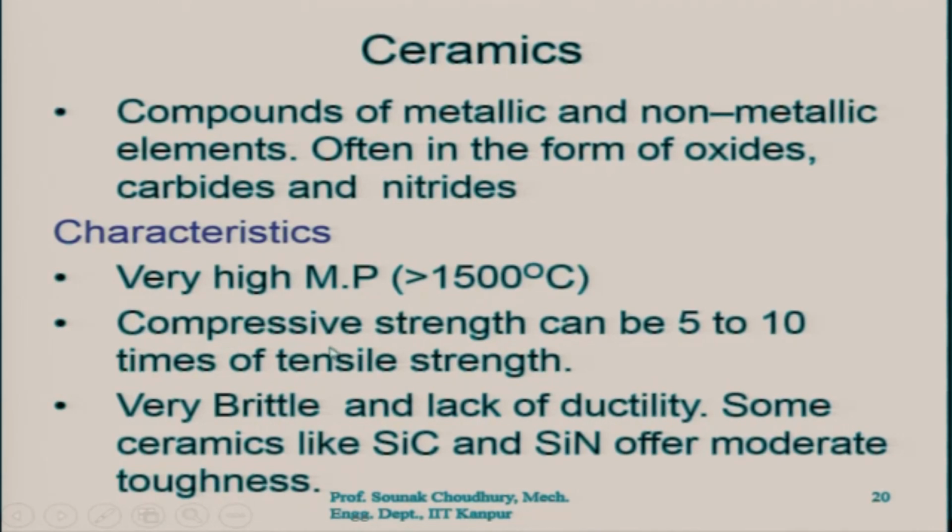Compressive strength can be 5 to 10 times the tensile strength. As you understand, these materials, ceramics, are brittle materials. Therefore, their tensile strength is not high, but the compressive strength is very high, up to 10 times more than the tensile strength. Because of that property, the high compressive strength, these ceramics are very often used widely. Very brittle and lack of ductility.